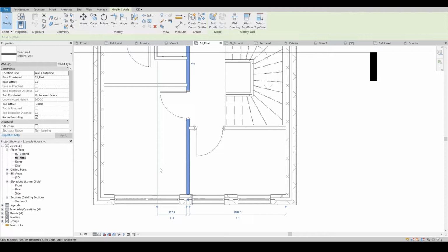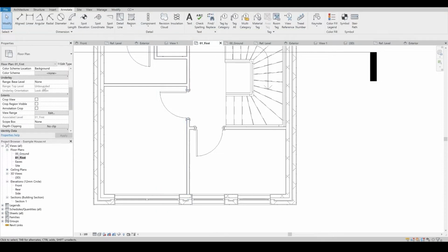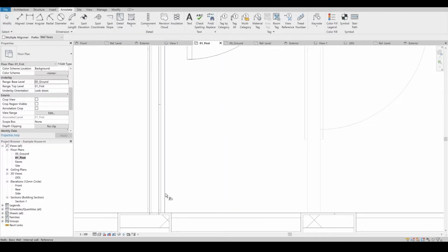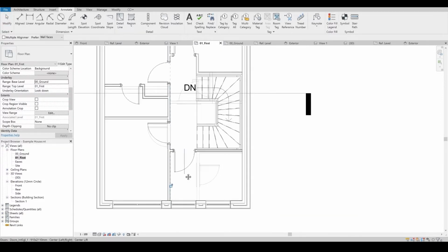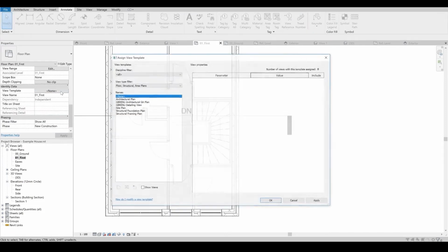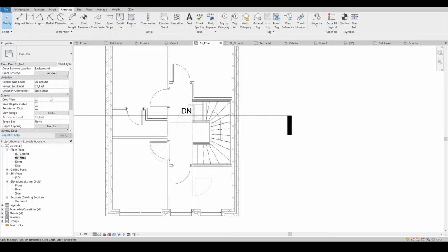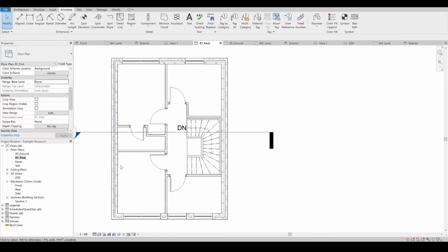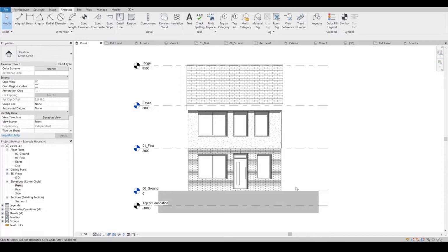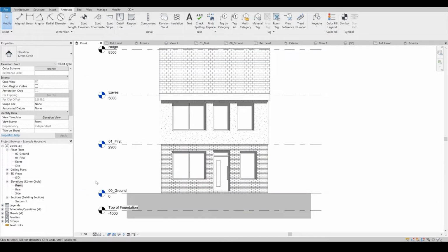100 mil. Now if you do underlay, really we want to align it with the wall below. So if we just, there we go, spot on. Okay, oh, cancel that. Where are we? Underlay, none. Okay, great. Front elevation, there we are. I mean, that's looking pretty good.